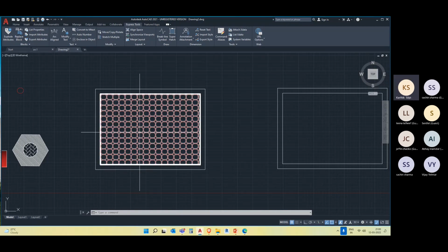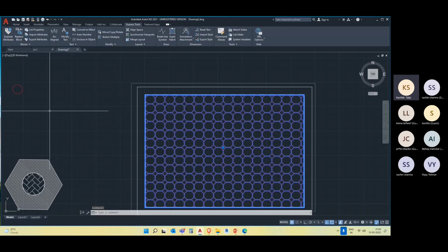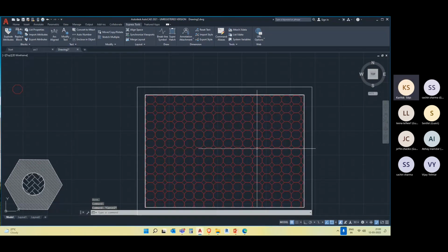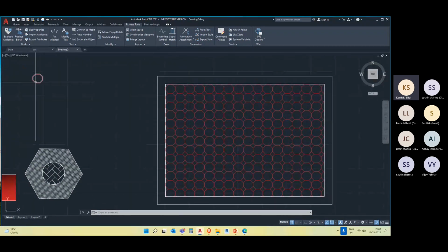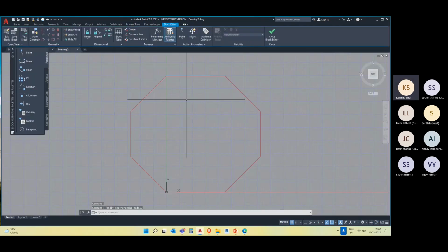And for example, let's say I am having an issue with this, or I just wanted to add some more parameters in this given shape. Is it possible once you have drawn? Yes, it is also possible. How? You have to edit this particular block. How can you edit an already completed block? You have to go for the block editor. You can just double click on that particular block. It will be selected. You will be greeted in a separate environment.